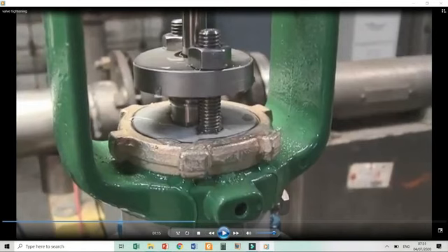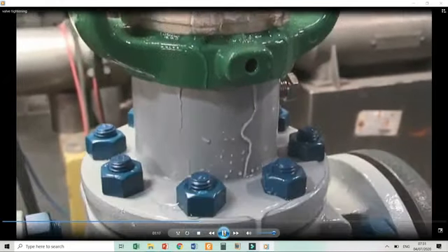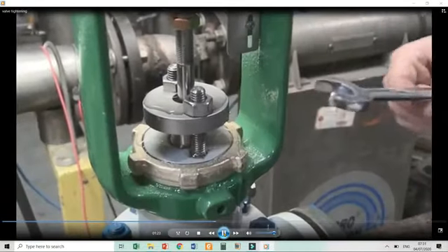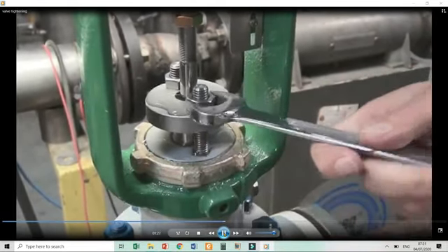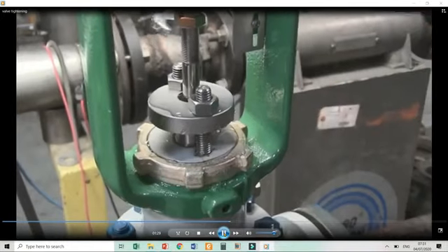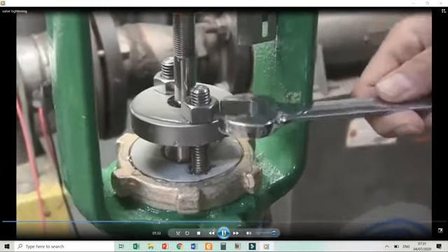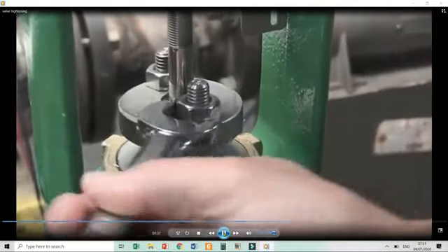As can be seen from this, there is a leakage of water or liquid from the valve. Here we see water weeping out around the packing and the valve stem. When you first notice this sort of leak, attempt to correct it by carefully tightening the packing nuts. I will use a 3/4 inch combination wrench and tighten the packing ever so slightly. It doesn't take much, just enough to seal the leak again.